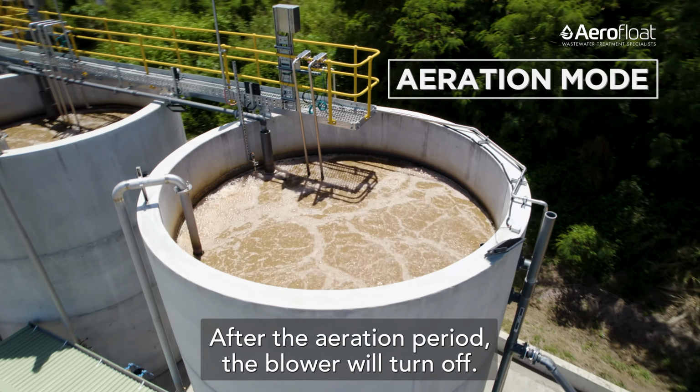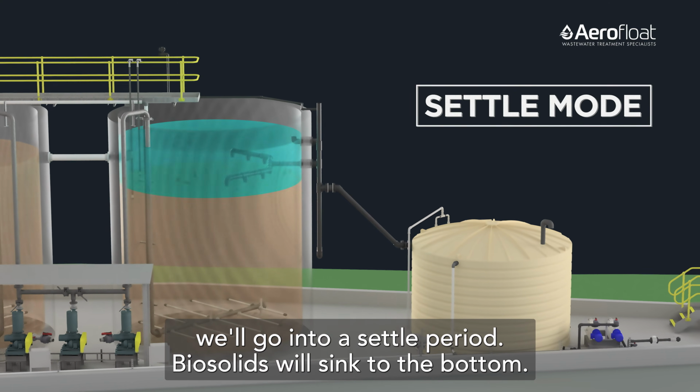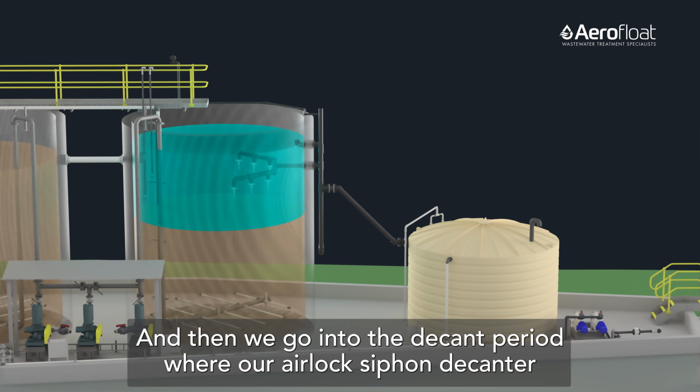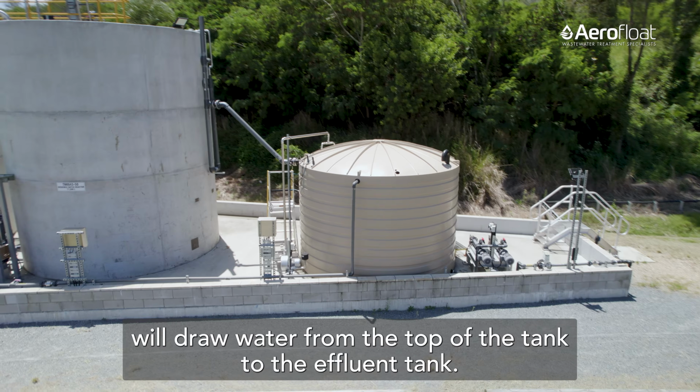After the aeration period, the blower will turn off, we'll go into a settle period, biosolids will sink to the bottom, and then we go into the decant period where our airlock siphon decanter will draw water from the top of the tank to the effluent tank.